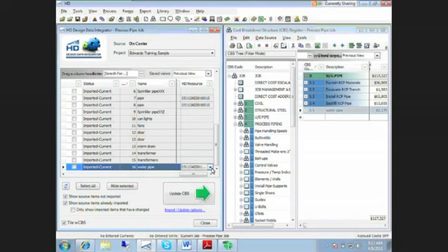And what you showed earlier makes sense to me because one of the questions I had asked early on when I first saw this was, could we bring those items over initially to set up the CBS, then circle back and bring in the assemblies, right? And I guess you could fudge it a little bit if you went back into the drawing and just added a tiny little increment to your takeoff. You could then come back and update existing cost items that you've already imported from OnCenter with the appropriate assemblies.